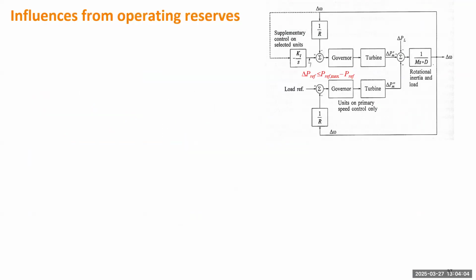Okay, next we need to discuss under what situations the AGC is available. It can be a very silly question. If you send the control signal to the setting point of the generator and through the integral controller, eventually it will keep feeding that signal until the frequency really goes back to the original frequency, right? But that is based on an ideal assumption, so there's no limitation on the controller or the capacity of control. But here we have to think about reality.